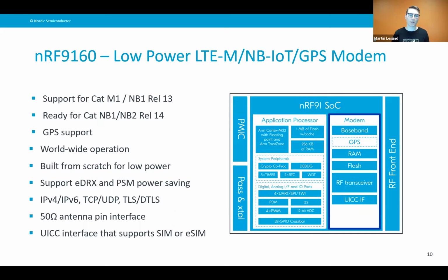So like I said earlier, it's built from scratch for low power. It's made by us in-house to make it as optimized as possible to low power. We have support for EDRX and power saving mode for power savings. And also we have all the IPv4, IPv6 stacks, TCP, UDP, TLS, DTLS support in the modem here. And also we have this 50 ohm antenna pin interface that you just connect the system in package to.